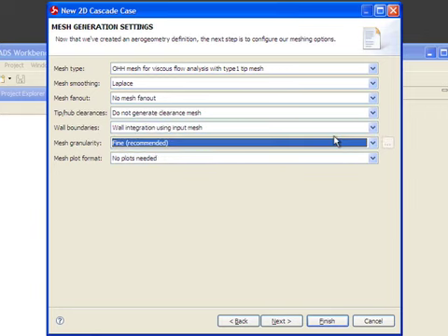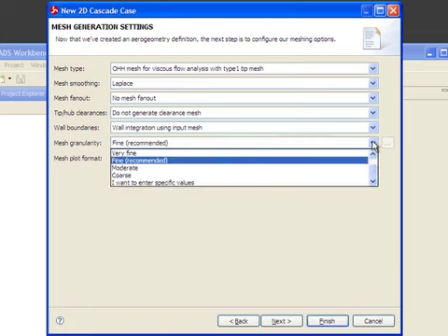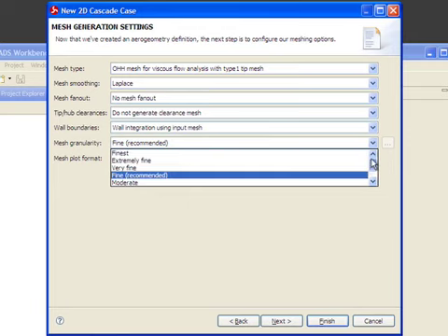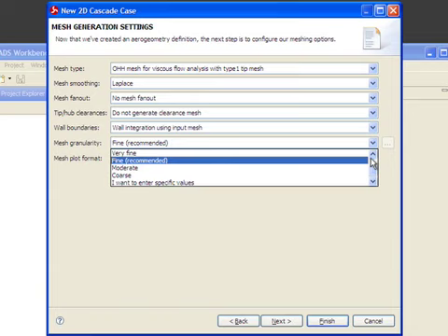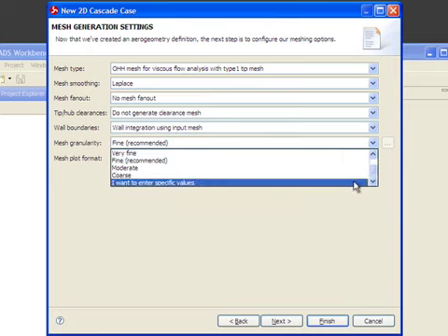The next step is to specify the granularity of the mesh that will be generated. There are a number of presets that we've provided that work well for us, anything ranging from extremely dense and finest granularity to coarse meshing. Alternatively, you can also be explicit about how many mesh points you want to have across various sections of the flow field.